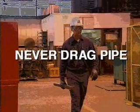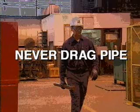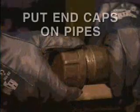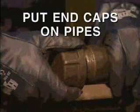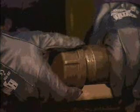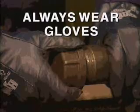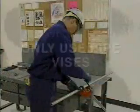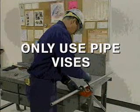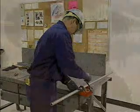Never drag pipes. Dragging a pipe can scratch or dent the outside surface, damage the ends, or contaminate sterilized pipe. Put end caps on pipes during handling and transport to guard against damage and contamination. Wear gloves to protect your hands from rough, sharp edges that could scrape and cut you. Only use vices equipped with special jaws for holding and protecting pipes. Conventional vice jaws can damage pipes.